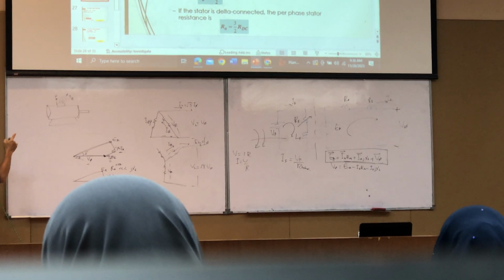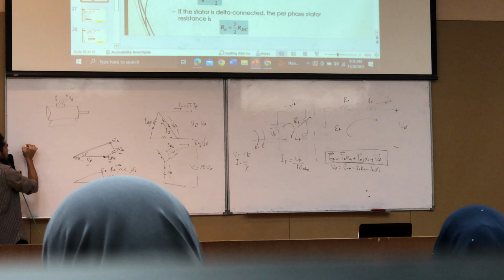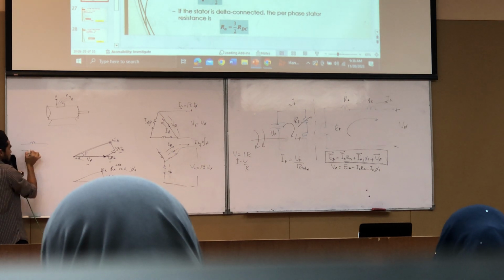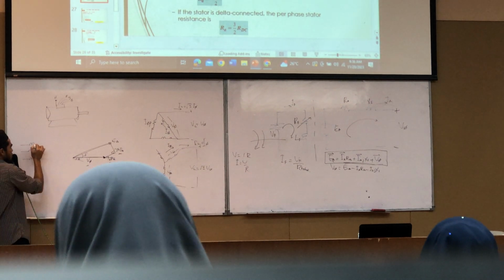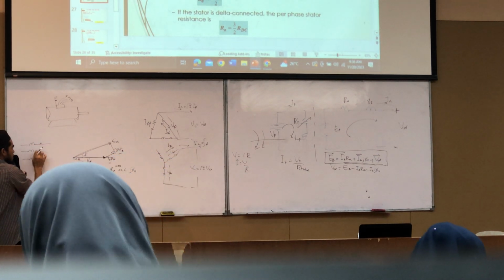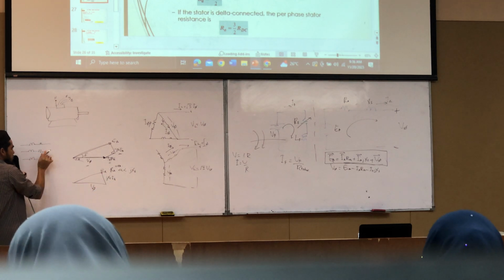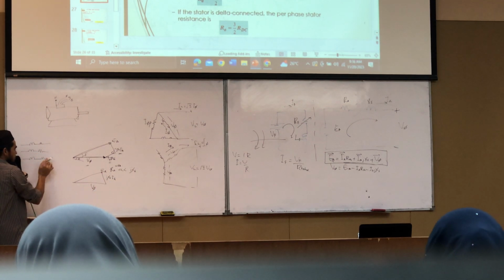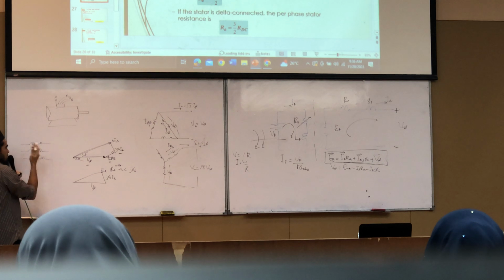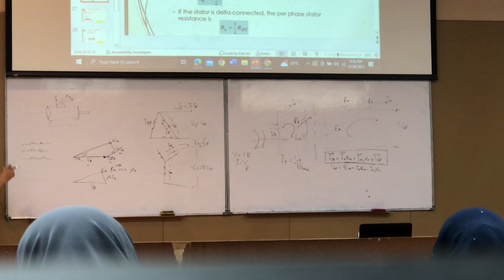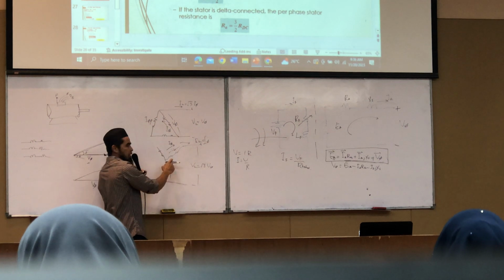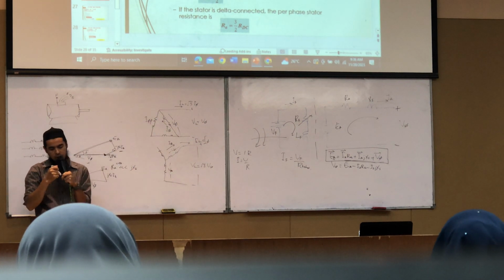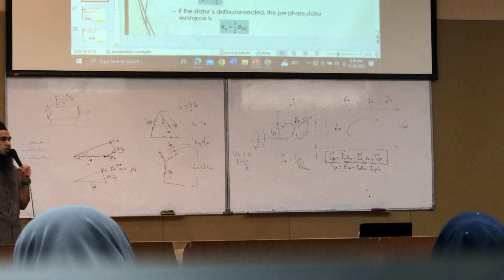And these 3 wires actually come from the 3 coils. We have only 3 coils inside your machine. And when you connect these coils, you will measure that one is resistive, one is inductive values. These 3 coils will be arranged for connection in delta or Y. That's all you can see inside a machine.